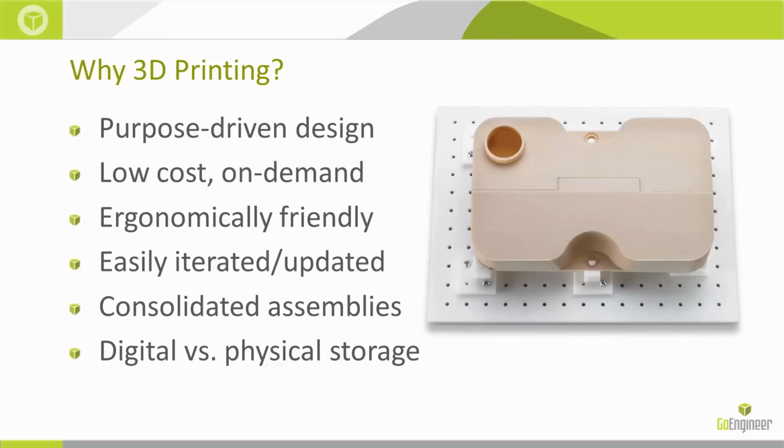It says, I'd like it to be a little bit lighter. This is hard to grip. I'm having trouble lining these two holes up. Get some feedback. And because it's 3D printed and because the cost in terms of time and money is lower, it's more easily iterated. It can be updated more frequently and more simply than if it was a jig or a fixture that had a lead time of weeks or months, which is not uncommon in the world, unfortunately.